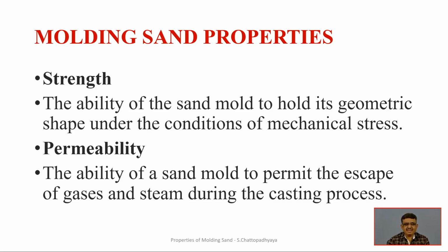So, the best strategy is that we have to give an appropriate escape route, and who will provide that? The permeability, that character of the molding sand, will give a good, reliable escape route.